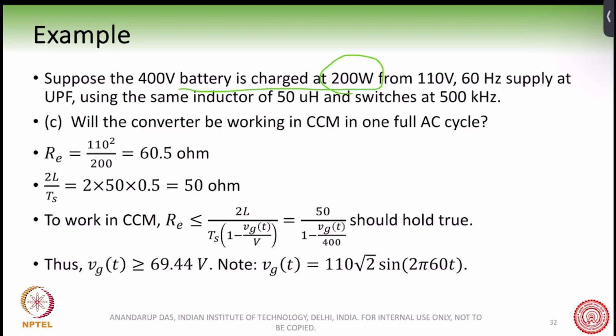So when the state of charge of the battery is less than a certain value, for example less than 90%, we say that we will go with the CC mode. And when the state of charge is more than 90%, we go into a CV mode. Now the power consumption in the CC mode and the CV mode may vary. So the whole point I wanted to discuss is that when you charge a battery, the power taken by the battery for charging is not constant. It can vary. It can be 500 watt initially, but it can go down to 200 watt at the end of the charging.